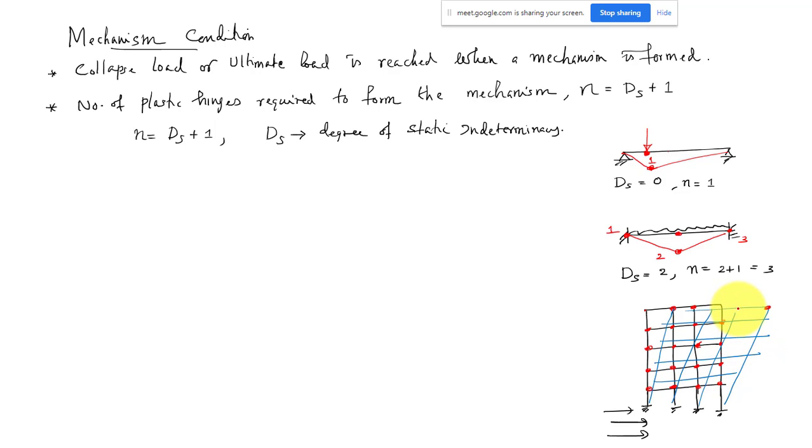There the plastic hinge will start forming. First it will form somewhere here, for example. Then this location cannot take any more load, and it will distribute the load to the other joint. And finally, the hinge will form there also. Finally, this plastic hinge will spread to the other locations. So many plastic hinges will form in the structure, and then it will form a mechanism. Once it reaches that mechanism stage, it will just collapse. Finally your overall structure will collapse.